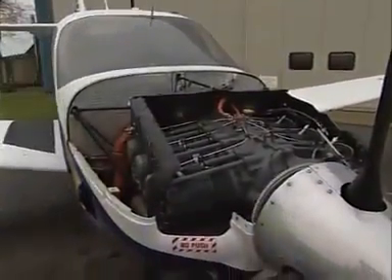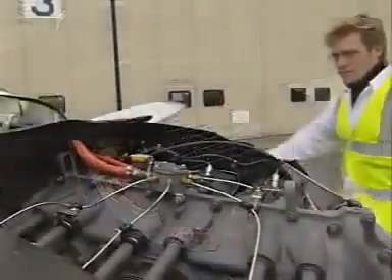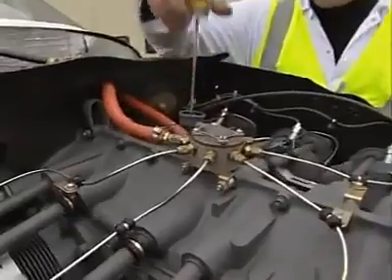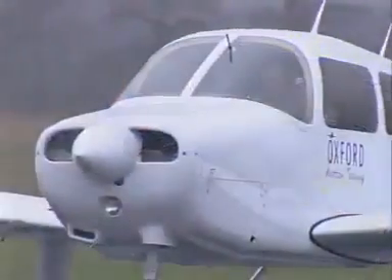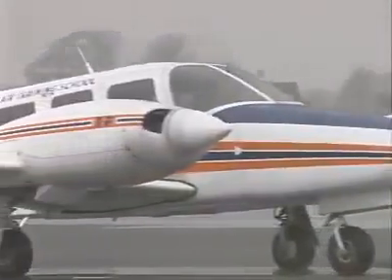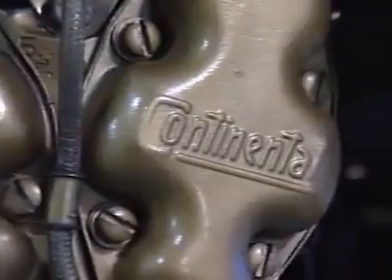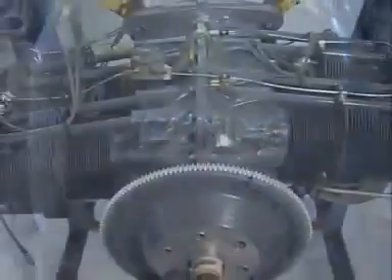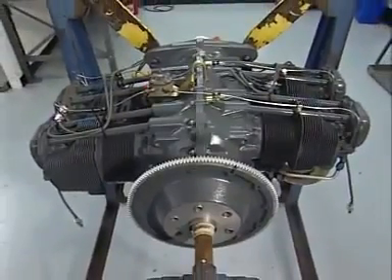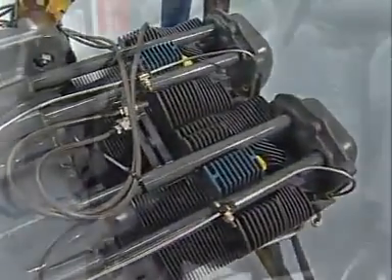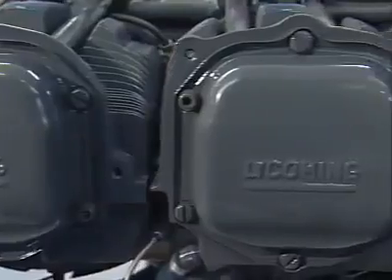Most general aviation aircraft are powered by simple air-cooled piston engines. The engine drives a propeller which provides the thrust to pull the plane through the air. The majority of engines in Western aircraft are currently made by one of two manufacturers, Teledyne Continental Motors or Textron Lycoming. Their products are very similar in layout and construction, with typically 4, 6 or 8 cylinders located opposite one another in a flat arrangement.